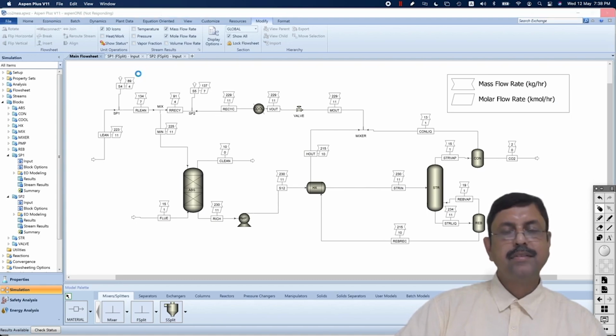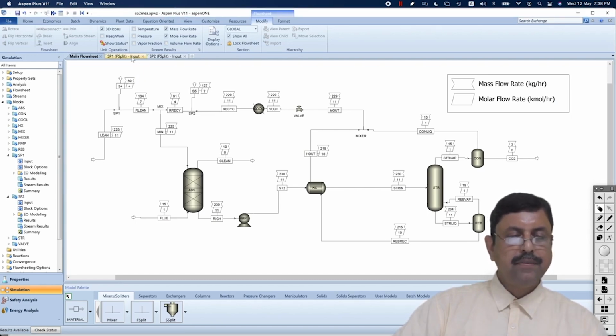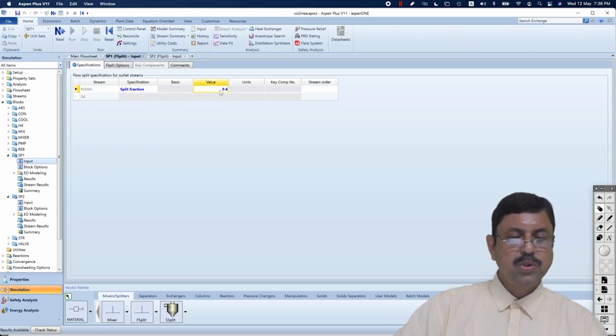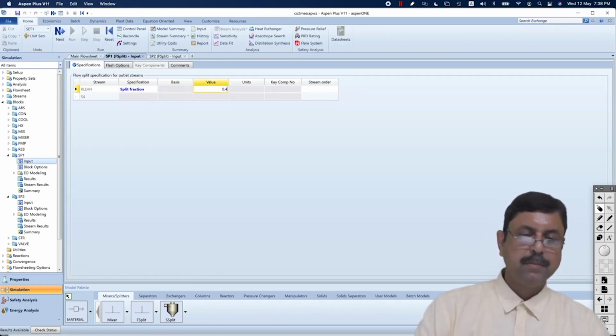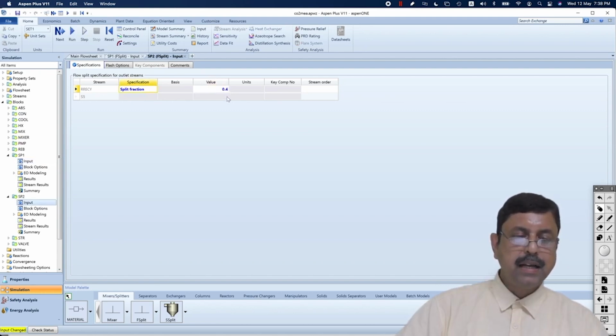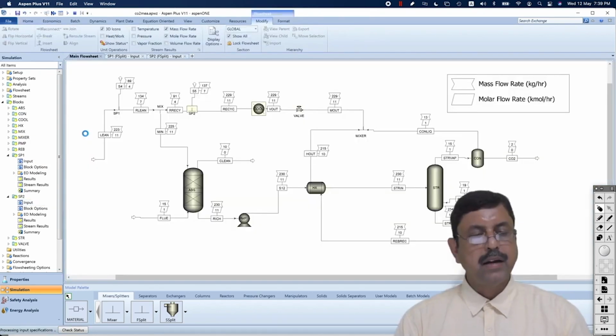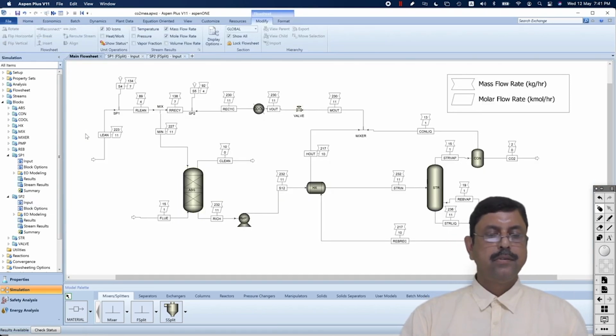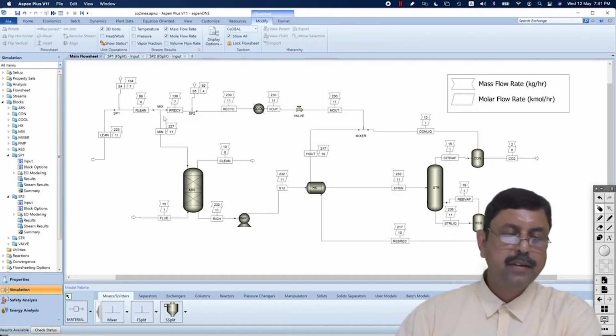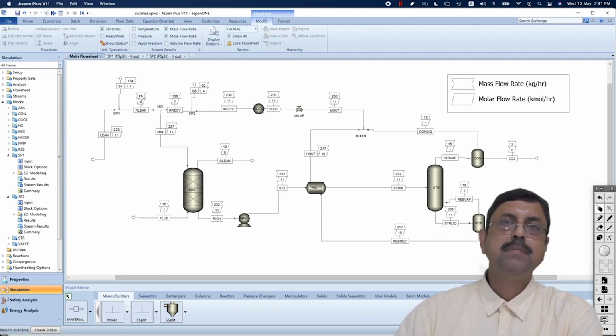So it gives us more confidence in decreasing the lean amine further to say 6 to 40%, another 20% jump, and lift the other one from 40% to 60%. Run once again. So it has converged again. Now you can see 138 kg per hour of recycle stream is being entered over here. Only 89 kg per hour of fresh amines.